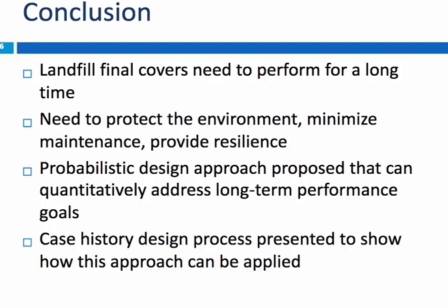A couple of final remarks. As many of our presenters have said, landfill final covers need to perform for a long time. We have clear performance objectives that we want to accomplish, some of which we can adequately quantify, some of which we cannot. What we were doing in this work is taking a probabilistic design approach that allows us to better quantify long-term performance in terms of settlement, which is not something that we have much tools to do at the moment. And then the purpose of this case history, of course, is to get a satisfactory design, but also to illustrate here how we might go about applying this probabilistic approach to sizing this landfill final cover.